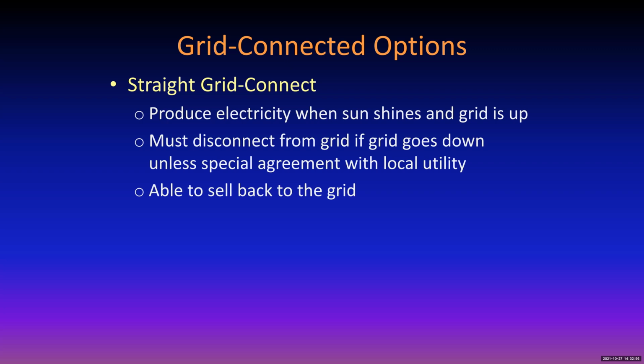Now, if the grid starts to fail, which happens sometimes in the afternoon when the utility is close to its peak, the last thing the utility wants is for the PV systems to shut off, because then it makes the situation even worse. So the utility wants that PV in the afternoon because it helps them out.